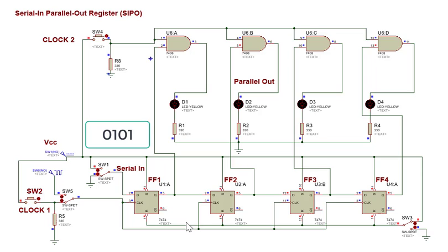If we continue to apply clock signal with SW1 in down position, there will come a time where all output levels of the 4 flip-flops become 0 or color blue. By permanently positioning the switch SW1 to up position and continuously triggering the clock inputs, you will notice that after 4 clock transitions from 0 to 1, all 4 flip-flops will have high logic levels or red colors for their Q outputs.